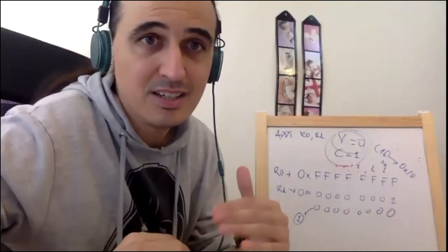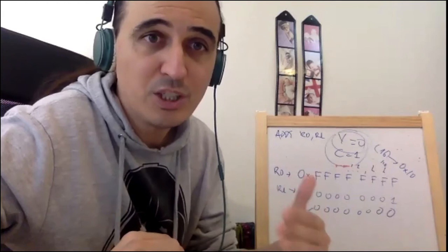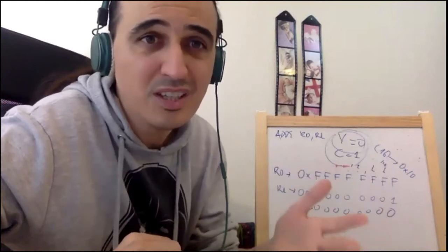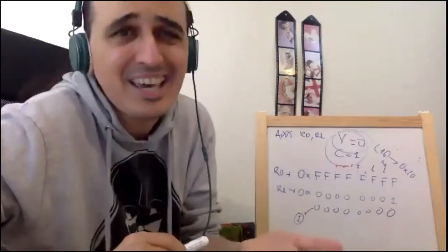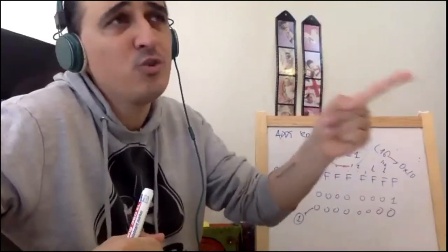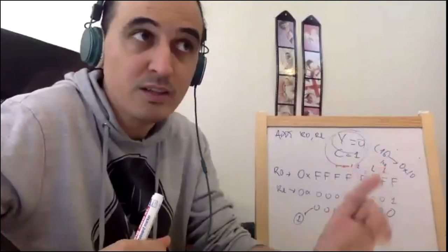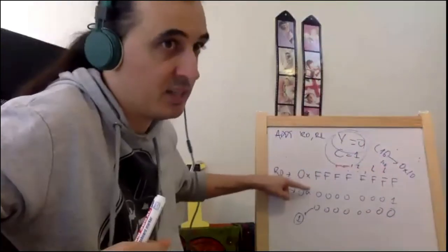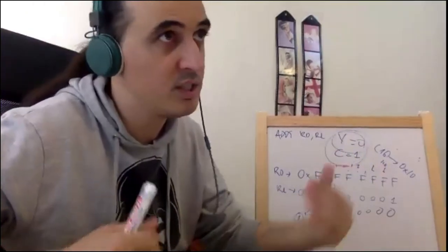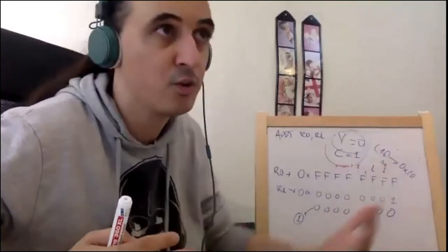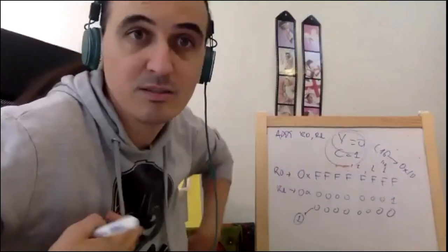So this is like trying to understand if the result is correct or not, depending on your operation being signed or unsigned. The microprocessor doesn't know what operation you are doing. You could be doing a signed operation or an unsigned operation. So in any case, it's telling you both: if you did this operation and they were signed numbers, it's okay, no problem, you can use the result. But if these were unsigned numbers, the result is not correct, because the result is 0 for me, and you're calculating a very big unsigned number, which is 33 bits. The processor is trying to tell us that this is wrong using these bits, guys. Okay?